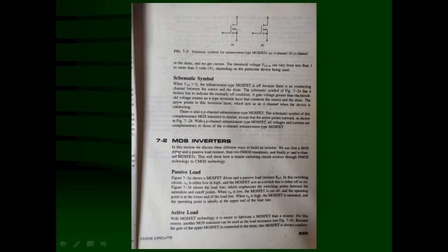That is the way we can explain the first type of MOS inverter. Figure 7.3a shows a MOS driver and a passive load. In this switching circuit, Vin is either low or high, and the MOSFET acts as a switch that is either off or on. Figure 7.3b shows the load line, which emphasizes the switching action between the saturation and cutoff points.